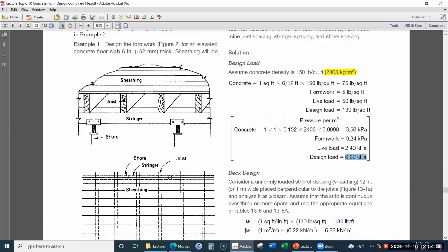By the bending criteria, it means there will be a load over here, and then this slab will bend, and at some point the bending stresses will be of such a magnitude that the slab will fail.